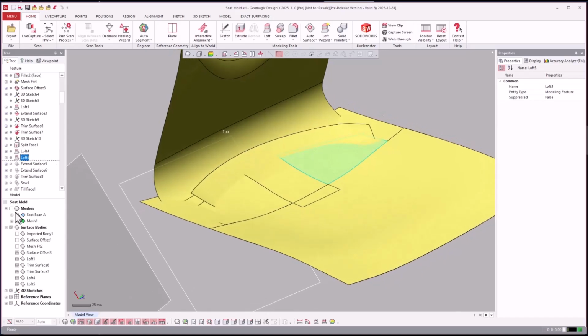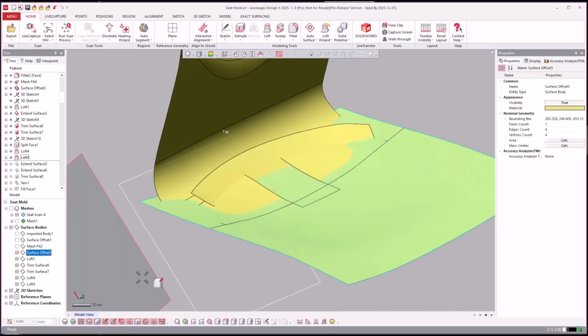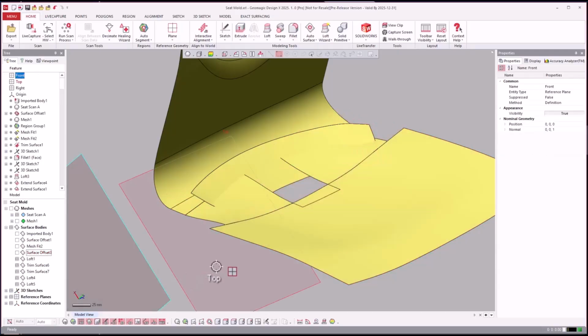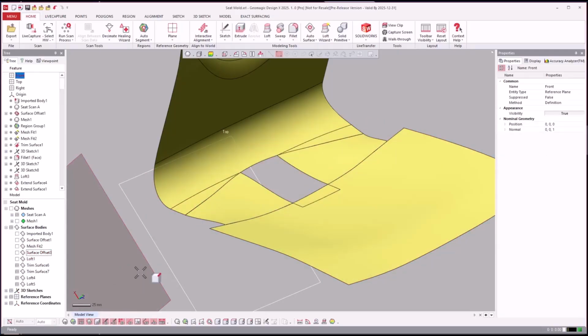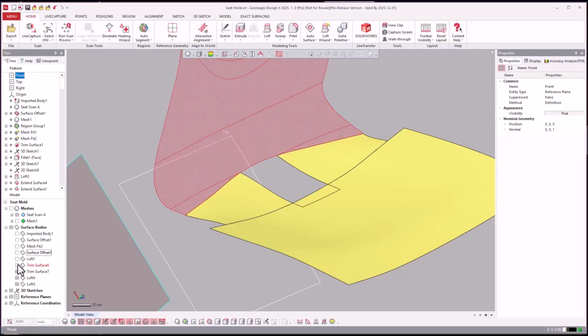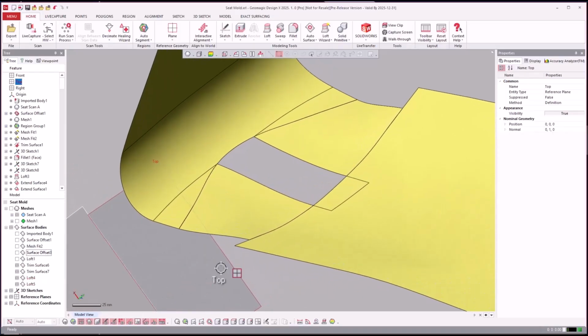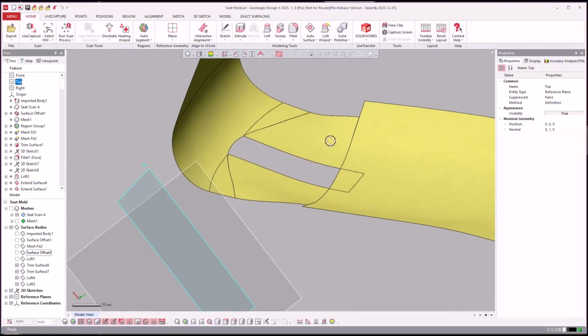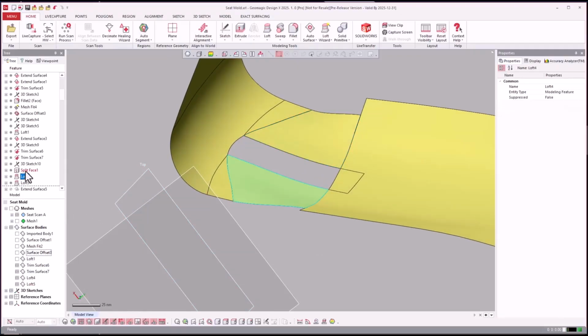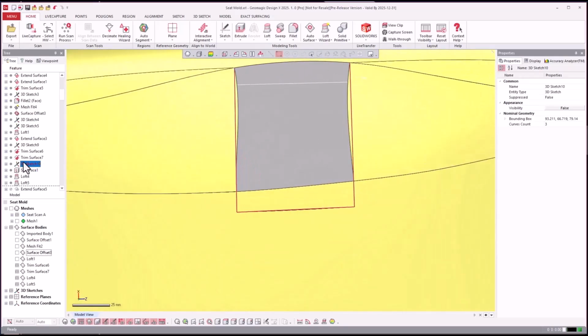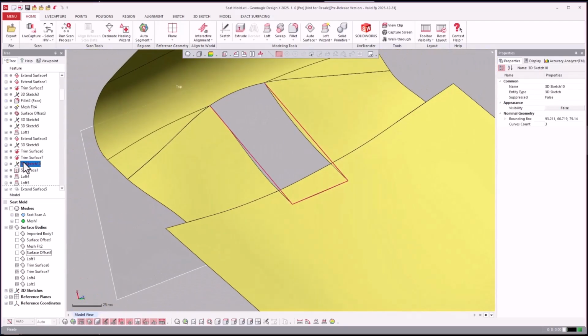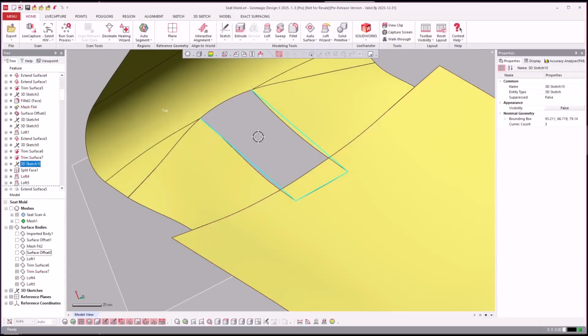And then lofted between those two. So let's go ahead and do a little bit of cleanup here. So we'll just hide some surfaces. Keep that one on, keep that one on. Loft, loft. Okay. So you see what's going on here is they took that blended surface and they created a split face using this. So they just drew a square out of the middle, and they used it to split the faces and then create lofts on each side.